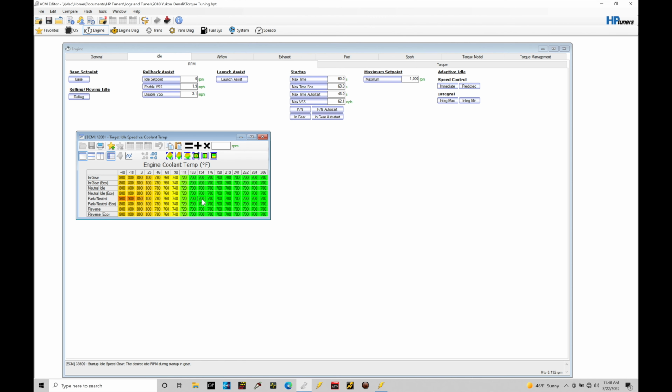Now what this is going to do is say that if I want to idle at 700 RPM, the engine control module is going to take a look at the target idle speed. It's going to take a look at the actual idle speed, or what the engine's actually running at, and it's going to figure out the deviation or the difference. That's known as the idle RPM error, or the difference between the actual and the target. Now that error is what's used to drive the torque-based language and control in terms of trying to reach that desired target. So there's always going to be a fluctuation there.